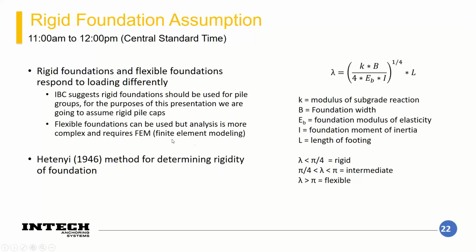And it's not to say that you can't use a flexible foundation, but a more rigorous analysis approach is going to be necessary if you do have a flexible foundation. You'll need to use finite element modeling to see how that's going to end up imparting load into your piles, and it's much more involved than going with a rigid pile cap.